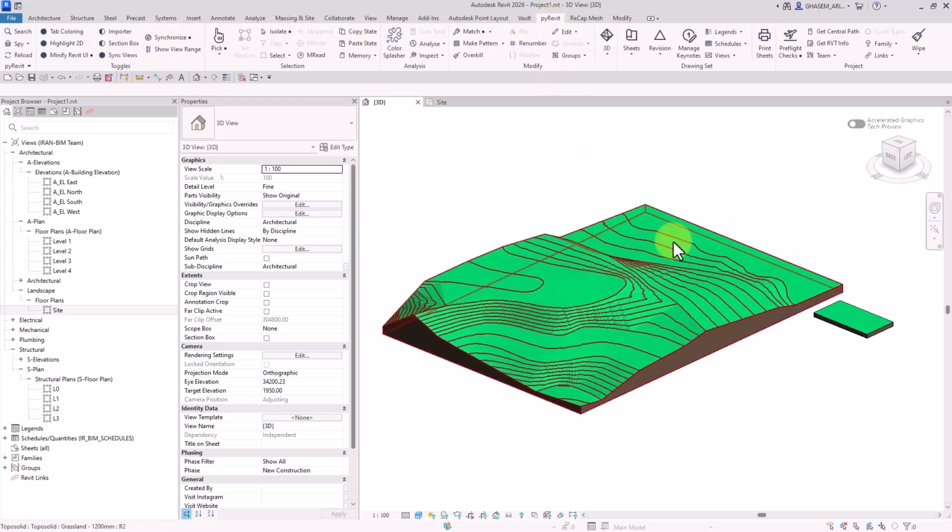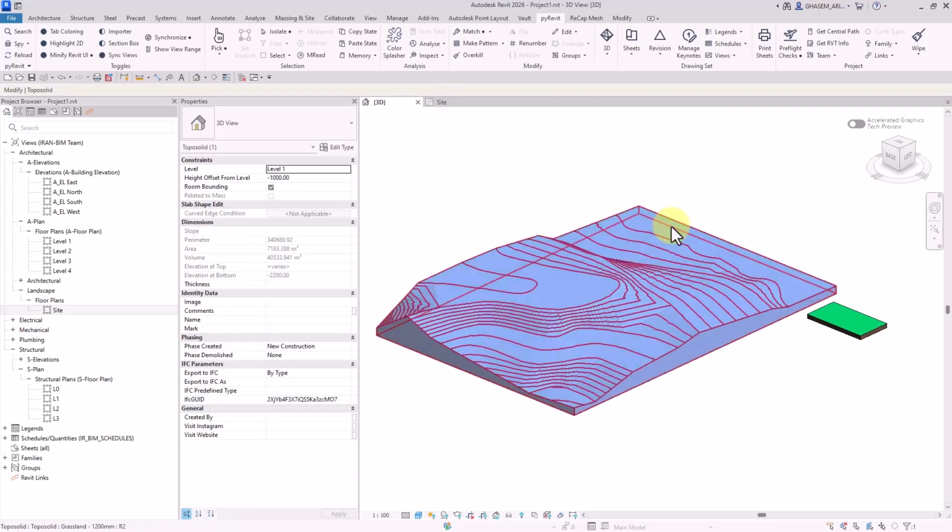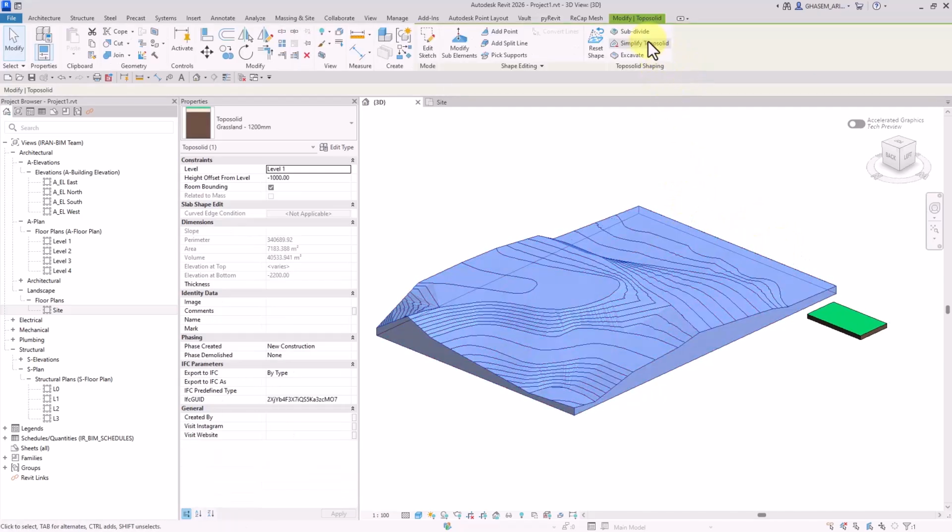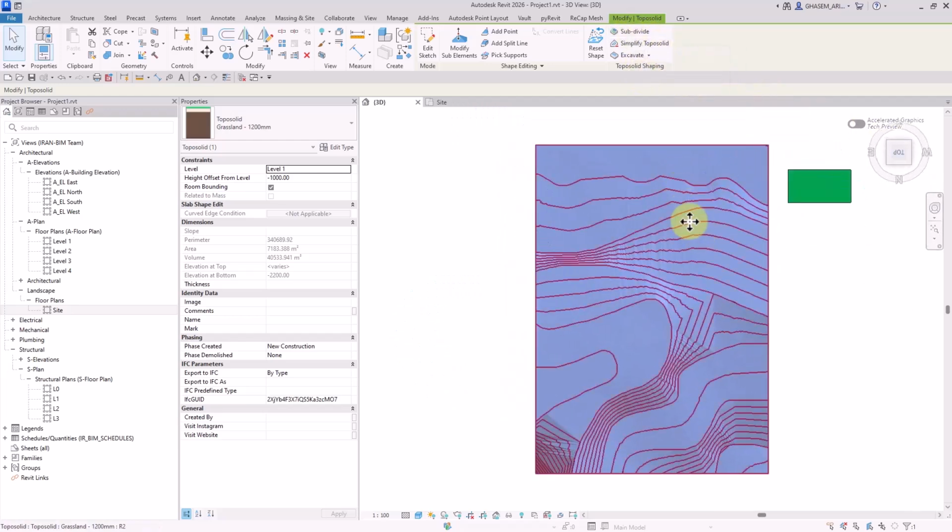Right. Let's talk about subdivision, guys. In previous versions, we also had subdivision, but we only had it as a sub-item of Toposolid, and we were only able to work on their materials. Now, though, it works completely separately as a separate item or command. It has sub-items such as offset. It's being used in the excavation-related processes quite accurately, and overall, it has gotten quite enhanced.